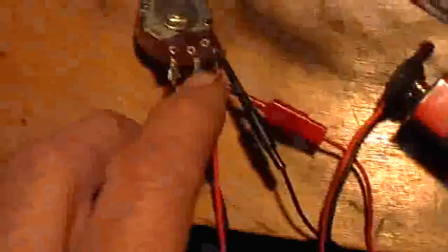Okay, so those go over to the circuit, and we've removed the timer altogether. None of this is in the circuit. The black wire, which is going to the battery positive side of the pot, remember, is going to the function generator positive connection point. Okay, and the red wire, which is hooked to the pot wiper, is going over to the function generator minus point, through a 50 ohm resistor.